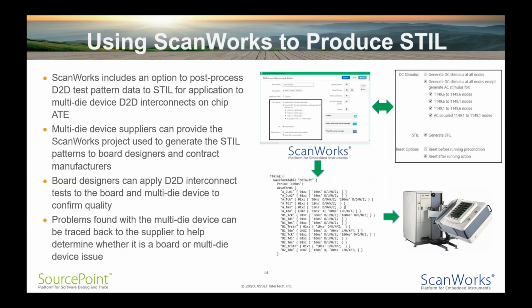The ScanWorks ATPG feature produces test patterns based on the chiplets' BSDLs and the package netlists describing how the chiplets are interconnected. Using the ScanWorks STIL option has several key value features for chip manufacturers and board designers. Multi-die device suppliers can provide the ScanWorks project used to generate the STIL patterns to downstream board designers and contract manufacturers. Board designers can apply die-to-die interconnect tests to the board and to the multi-die device to confirm its quality. Problems found with the multi-die device can be tracked and traced back to the package supplier, who has the same test on their ATE to help debug whether it's a board or multi-die package issue.